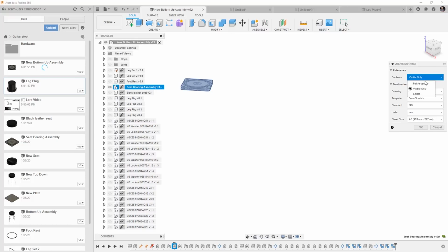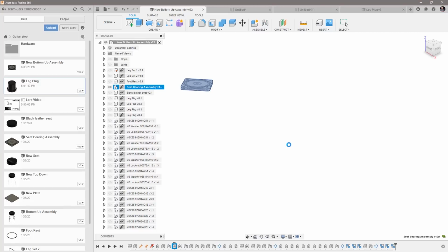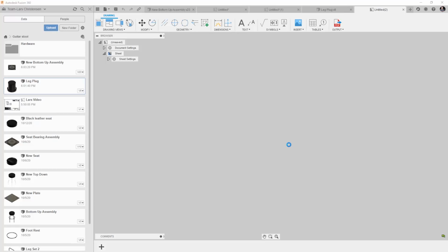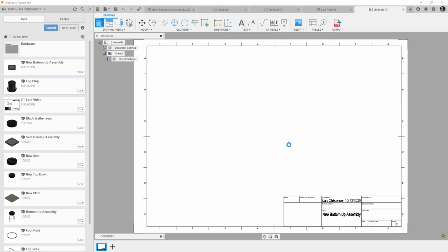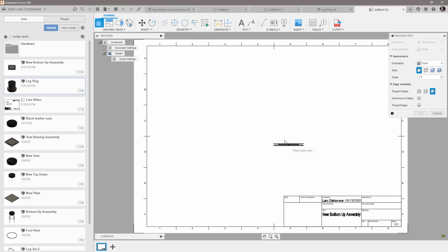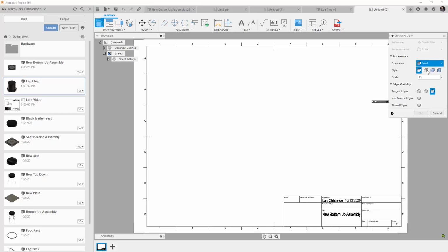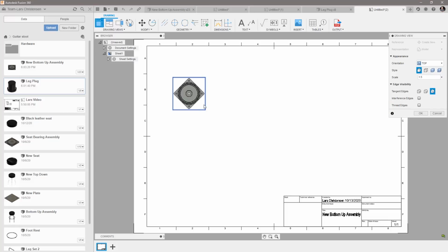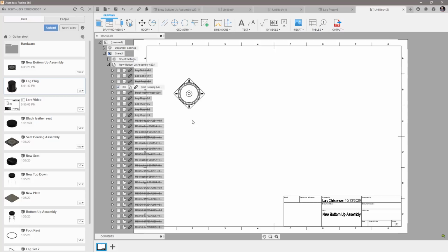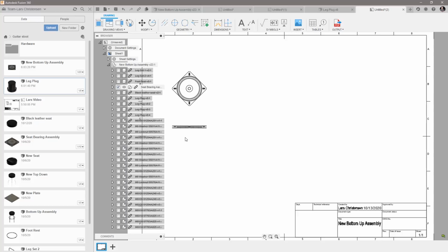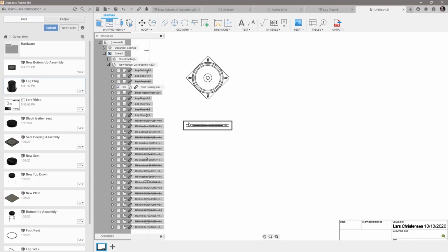notice that there's an option over here. You can select the full assembly. That's what we had before. But now it's visible only, and it would actually create a drawing only of this, only of our assembly bearing here. So this is a super nice way, I think, to break down, if you want to create different drawings for your assembled parts, is to use that visible only.